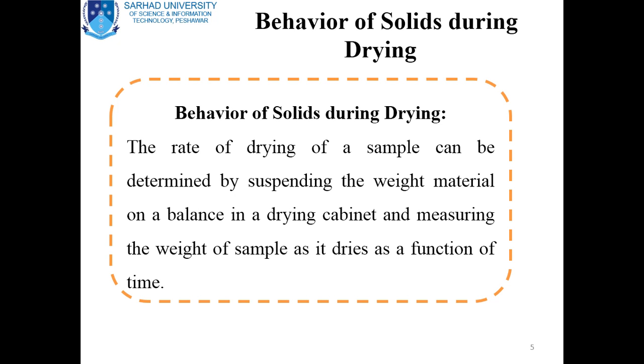By using these readings before the drying and after the drying, as well as the time taken for drying of the sample, we get the initial wet material, solid with solvent, and the dried material.